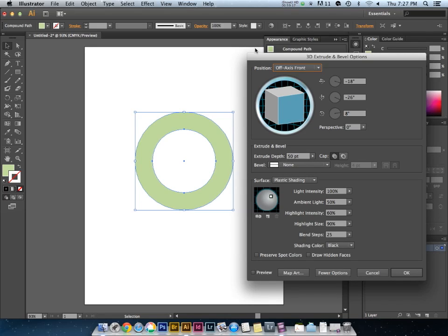And you'll see that it looks very similar. The first thing you want to do, of course, as I mentioned earlier, is click on Preview. And this time, it's not revolving the object, it's extruding it. It's taking it from a flat object and pushing that two-dimensional object out to create a three-dimensional object.